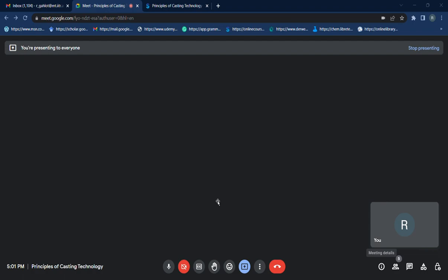If you talk about scab, do you know why scab happens? No idea, I forgot. To differentiate, firstly go and see the shape of the defect. Scabs are usually round or oval shaped. They may have irregular shapes also, but usually they are round or oval. Another thing is they occur by splash or some boiling or casting or conditioning defect.